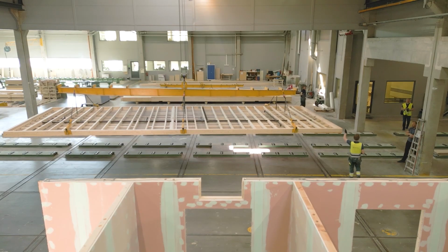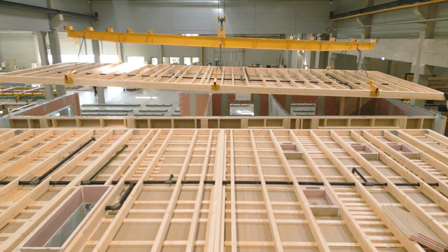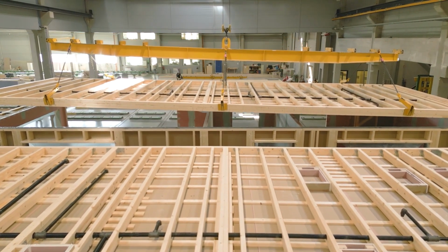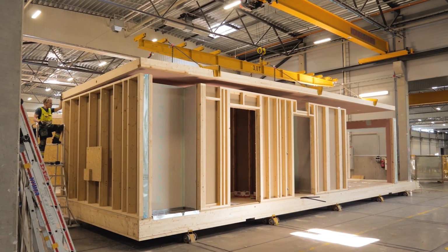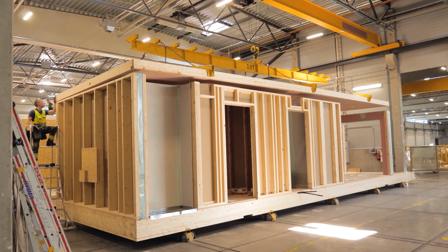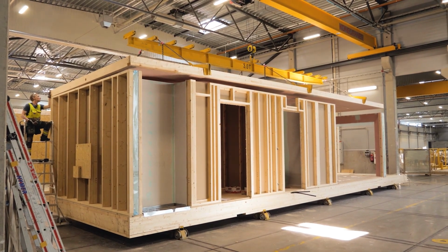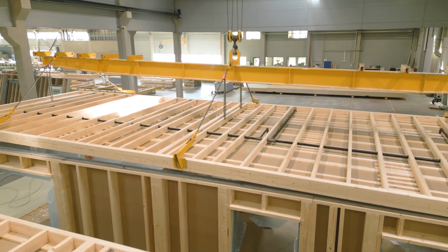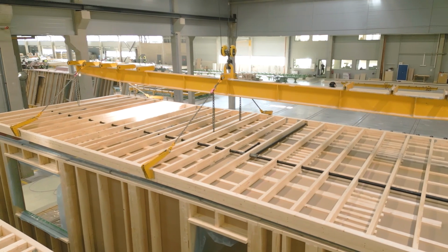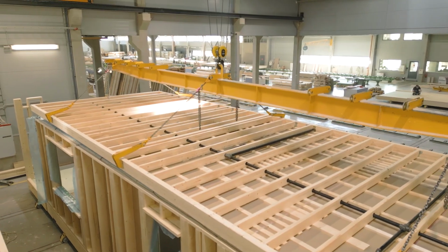If all the wall elements are installed and fixed, then lastly, the ceiling element is raised in its place. The attachment of the ceiling element to the wall elements must also be airtight. The airtightness of the joint is ensured similarly to the floor, either with glue or sealing tape. Attention should also be paid to the vapor barrier film, as well as its connection with the vapor barrier of the wall element. Both the installation of the ceiling panel and all joints must be carried out in accordance with the technological solutions described in the company work instructions or developed by the project designer.